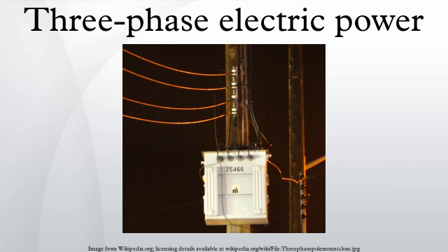Wiring for the three phases is typically identified by color codes which vary by country. Connection of the phases in the right order is required to ensure the intended direction of rotation of three-phase motors. For example, pumps and fans may not work in reverse. Maintaining the identity of phases is required if there is any possibility two sources can be connected at the same time. A direct interconnection between two different phases is a short circuit.